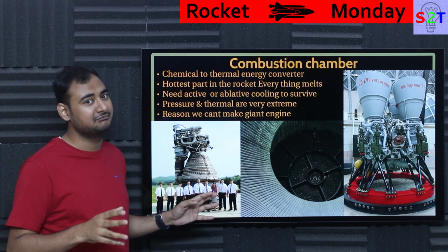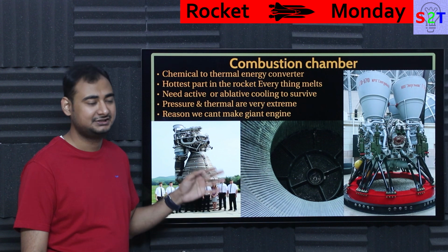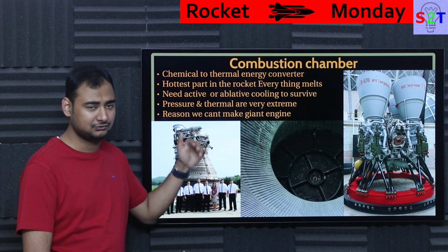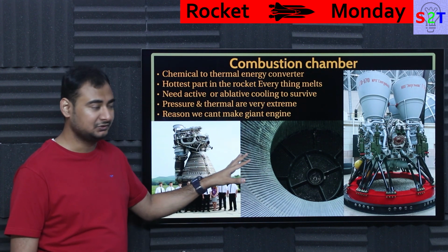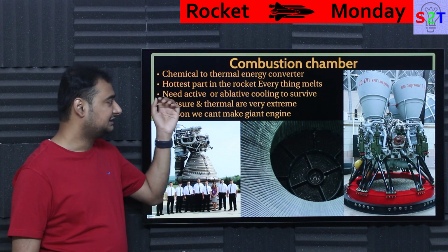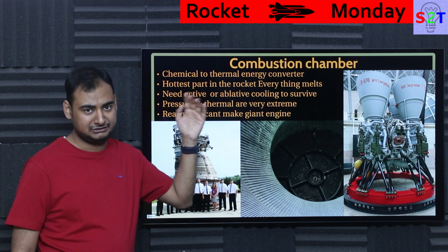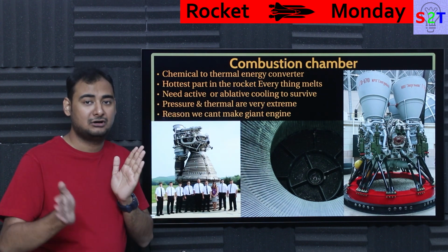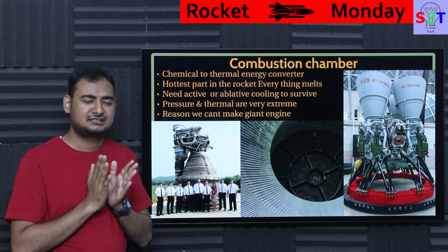It's just like if you have metallurgy that is strong enough, you can do it. Generally, they prefer to just fuel cool it. That's one way of cooling it. Better way of cooling it. But there is a cheaper way, that is ablative cooling, meaning you will put something there that will burn off, and you will like, doesn't that sound counterintuitive?